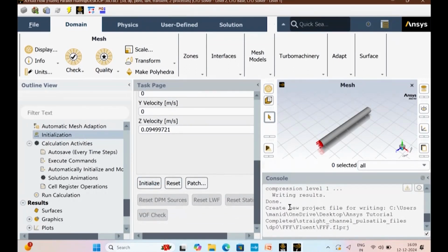Because the simulation is starting from the inlet, if we provide this type of velocity profile, will they take a constant velocity, or will it be a parabolic type of profile? This profile is time dependent, meaning on the x axis we have time and on the y axis is velocity. If we draw velocity at a cross section, it will be parabolic for this case. But when we do simulation in a bifurcating channel or channels having stenosis, like converging diverging channels, flow separation can occur. I am talking about the inlet. Yes, it will be parabolic.